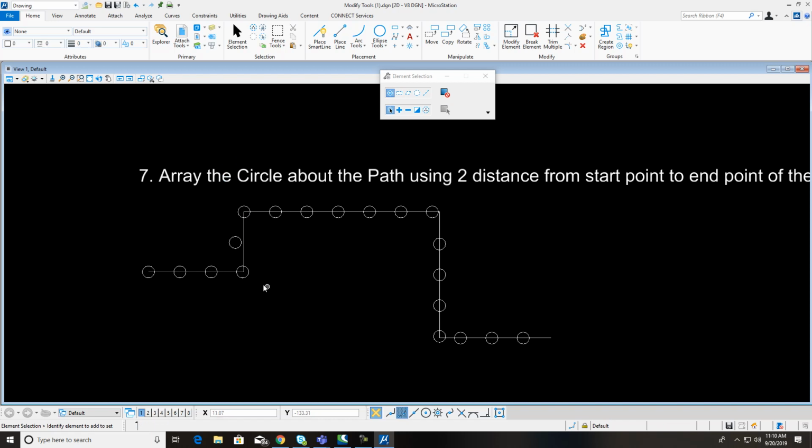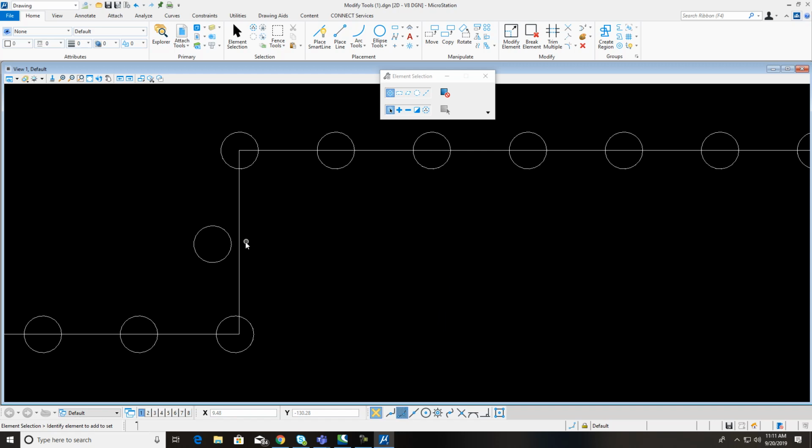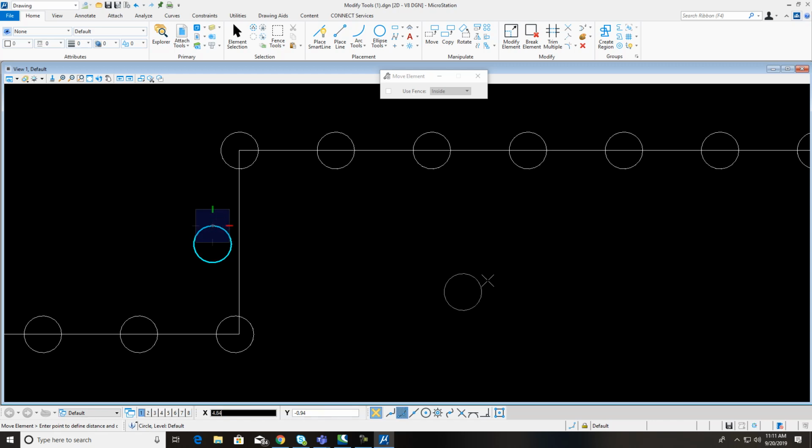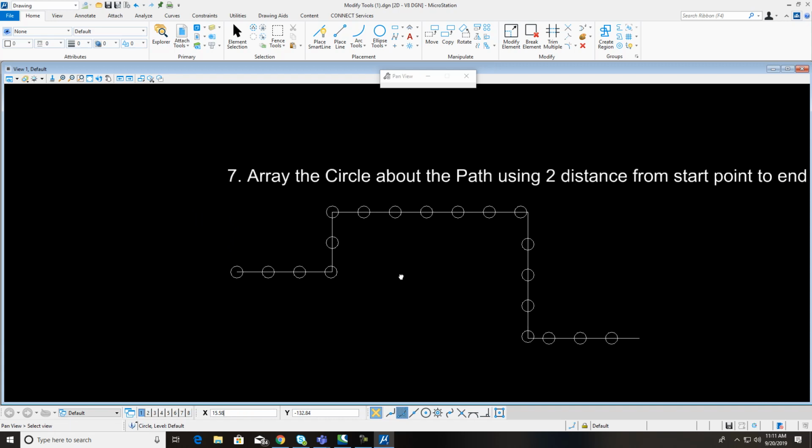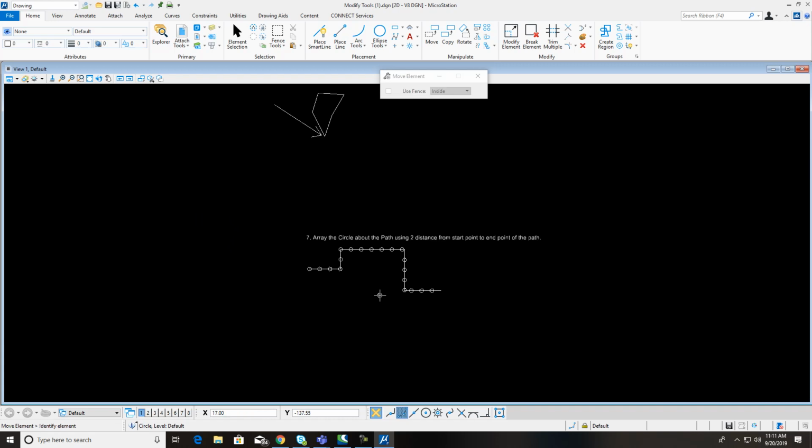And you notice that it's a little bit off on this one, and that's just because of this line, the way that it is. Puts it in, puts it across. All of them follow path except this one. And you know what we could do if you want to put that in the path? Let's just use your move command. And again, you guys use move, click on it, and I'm going to bring it straight over. And I want to hit perpendicular to that. And to do so, I turn on my perpendicular entity snap, click it right on there. Okay? So those are things that you can do, and I think that's all of them.